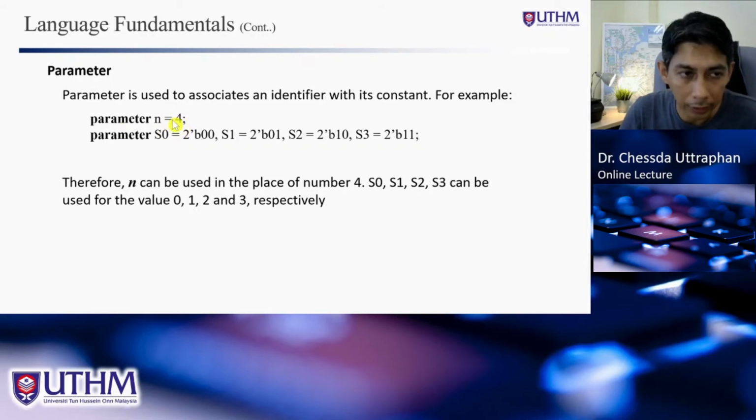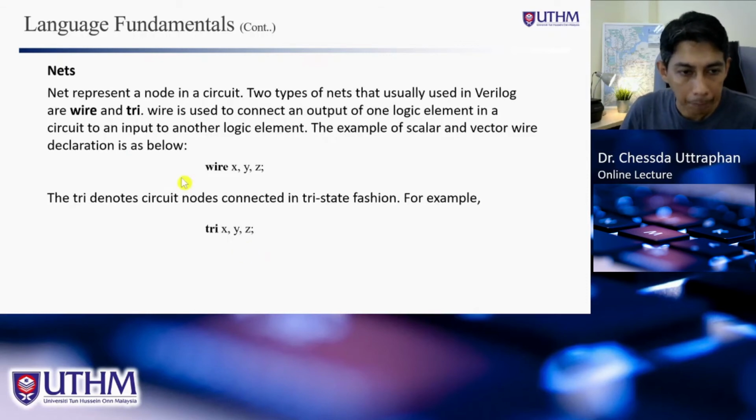First we set it to 4, which means that everything after this is 4-bit. But when we want to improve our design in the future and change to 8-bit or even bigger, we can change this number only, and everything after this that is represented by n will be changed to 8 or 16 or even bigger, right?